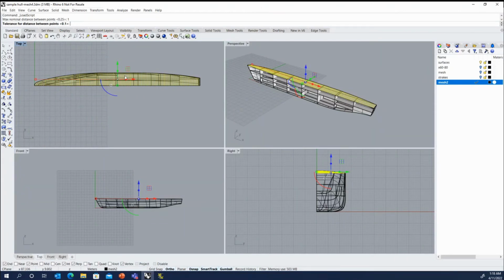Now, the other thing, when you go to create the mesh using this method, the curves need to be continuous. So if your deck surface had openings in it for hatches, or if you're doing a bulkhead and there were doors in there, you would probably have to defeature the surface and close up those holes. And it's very easy to do in Rhino, similar to the trim command. You can right click and it'll untrim a surface.